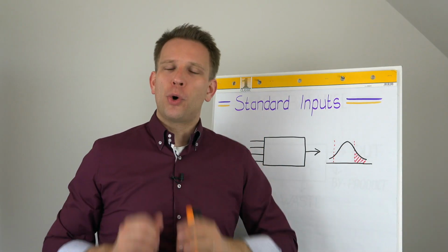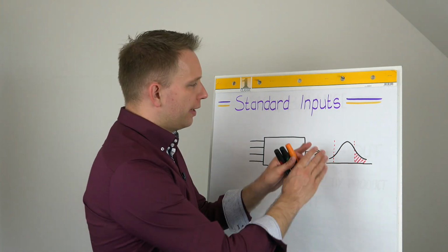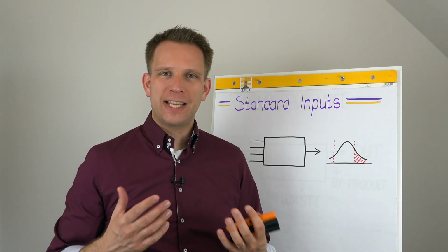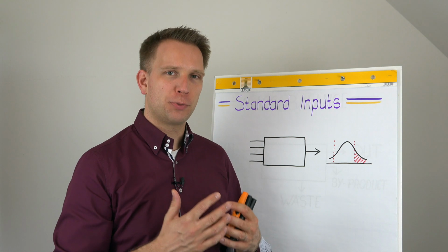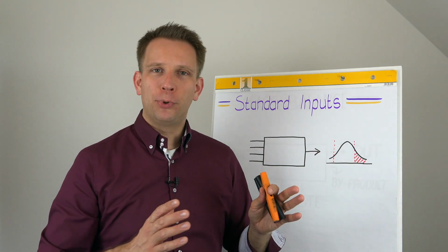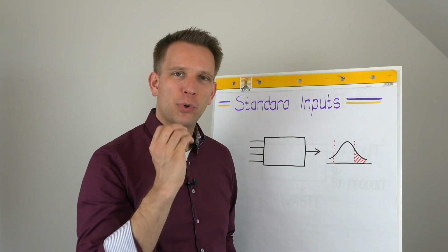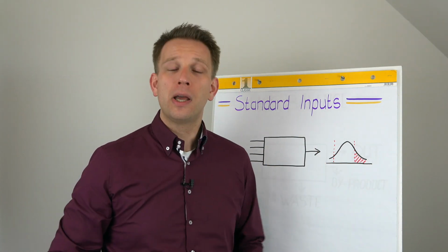But what I also often see is that when we have processes with a relatively high spread, so a low process capability and a lot of defects because they are not up to specs, we start checking more and more on the output, and we give operators a target: make sure that you get a more stable production process and that the products that come out are more stable.